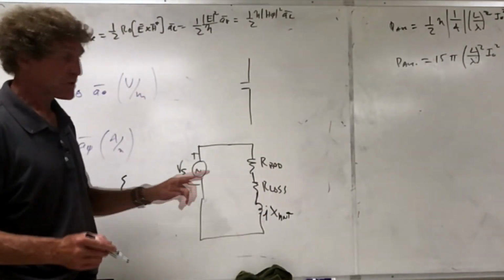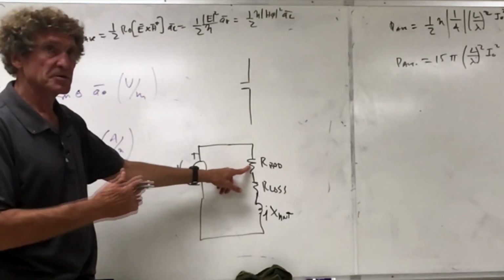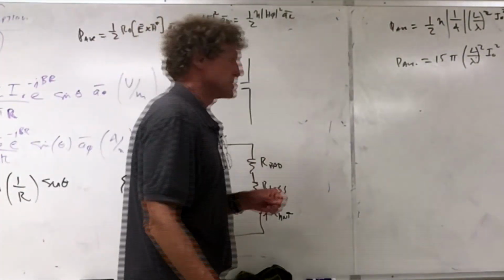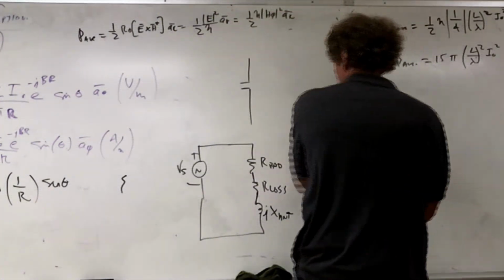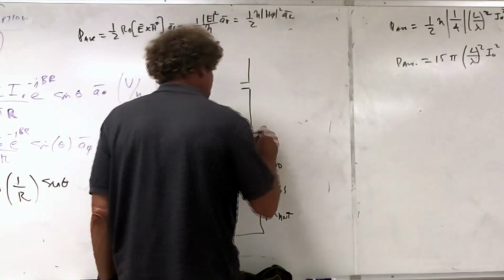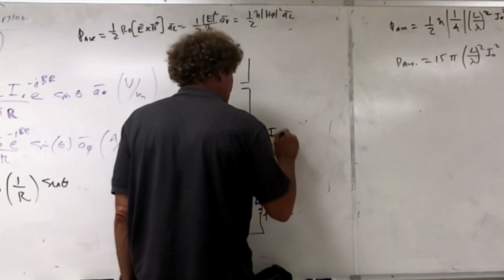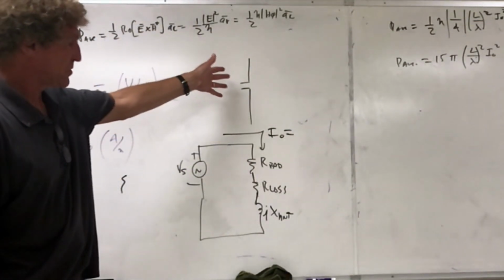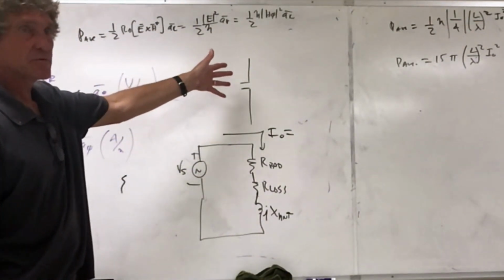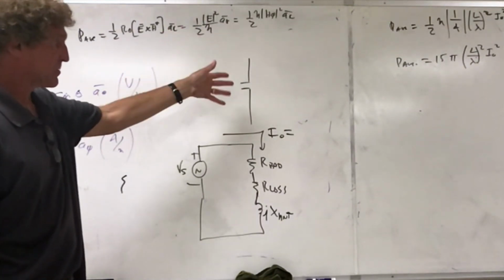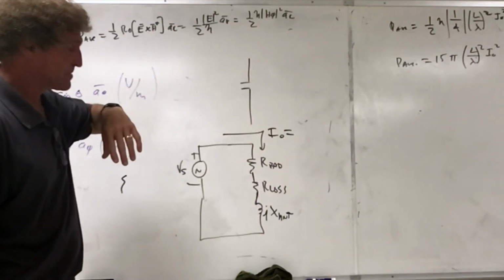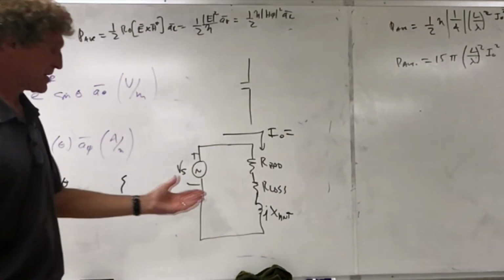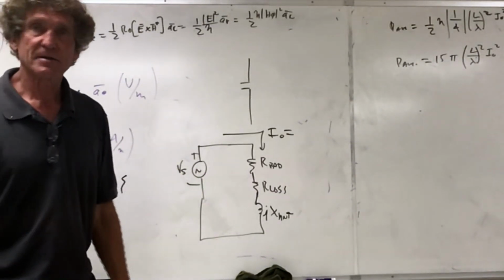So the radiation resistance is associated with the radiated power. You with me? And the way this works is that, let's assume there's a current flowing here. How would you calculate the current that flows if we knew what the actual radiation resistance was of the antenna that I'm about to put down, and the resistive losses, which we'll show you how to calculate, and the actual value of the reactive impedance?